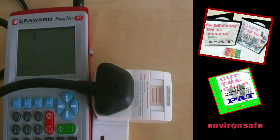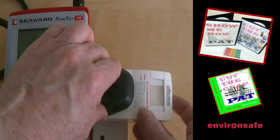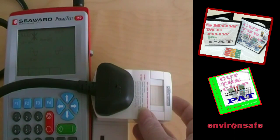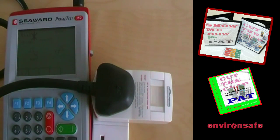This test is done in two parts. Press the green button, and the first half of the test is done, and the RCD trips in 18 milliseconds. And when I reset this RCD, it will automatically trip. And that was the second part of the RCD test in 16 milliseconds, which is well within the limits.